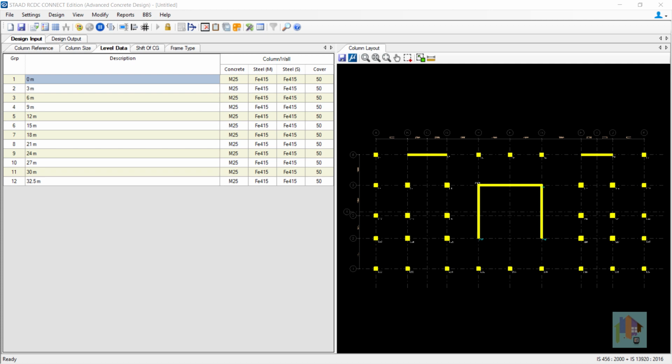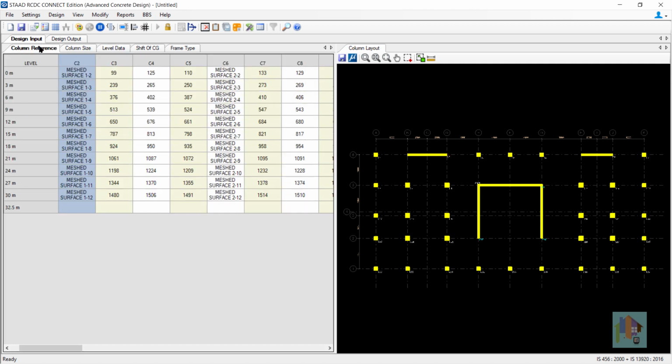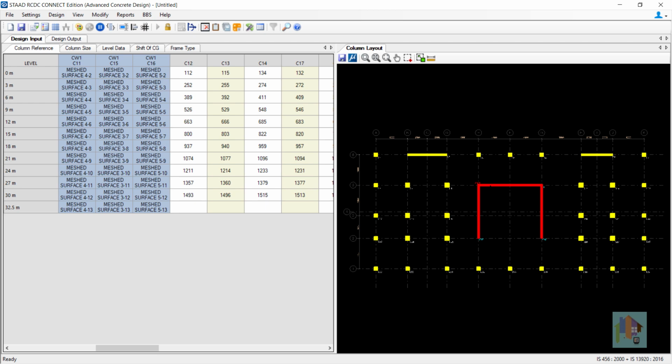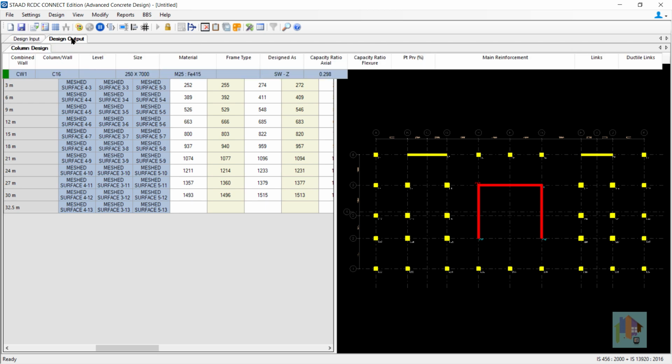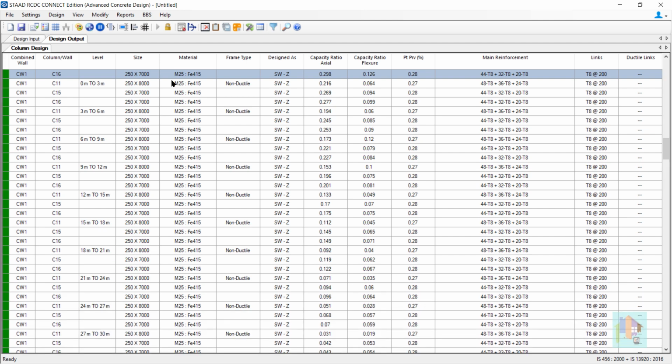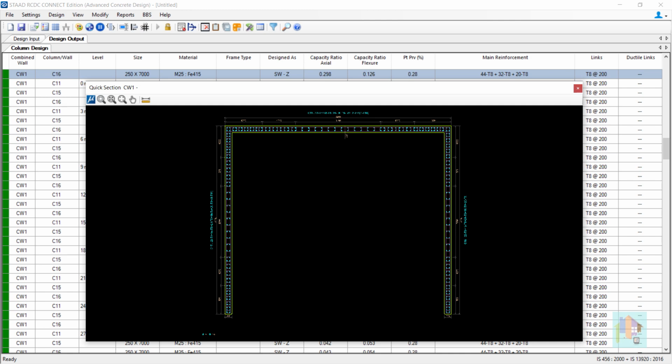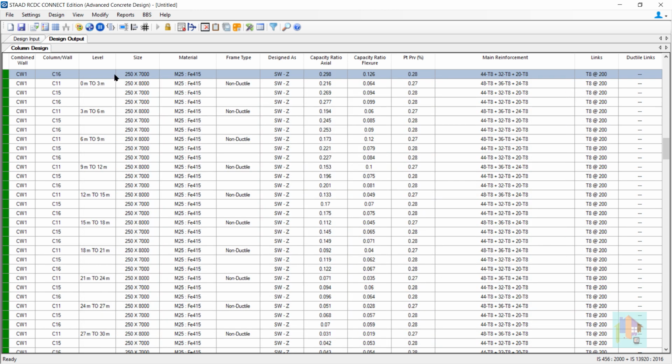In this model, walls are modeled using parametric model, hence all are imported, and we can design individual shear walls or the combined lift core wall using FEA result. In RCDC, multiple interconnected walls are considered as combined wall, though each wall is designed individually, neglecting the combined action. For the overlapping zone, maximum reinforcement is provided considering the design result of both walls.